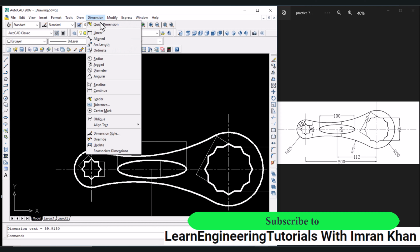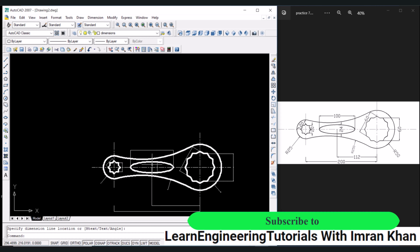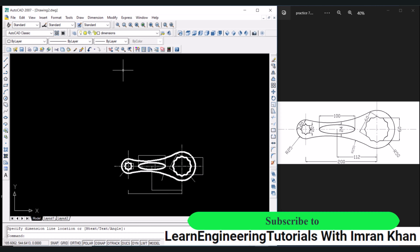Now go to dimensions, click on radius, click on this arc, move the cursor away and click. Press enter, click on this arc, move the cursor away and click. Press enter again, click on this circle, click. Now the dimensioning is complete.